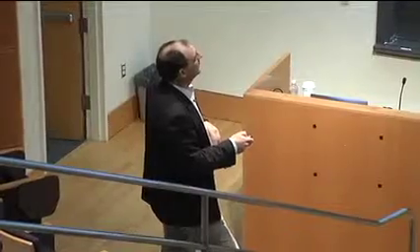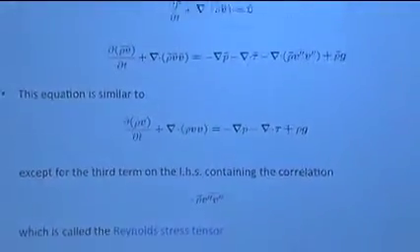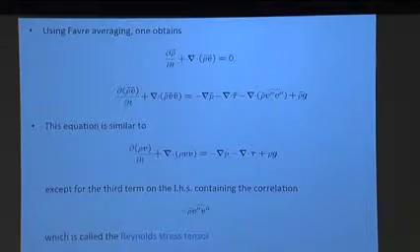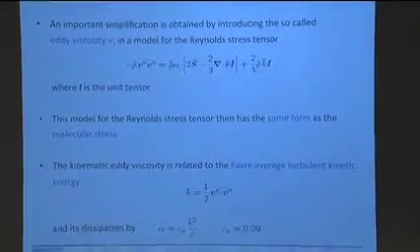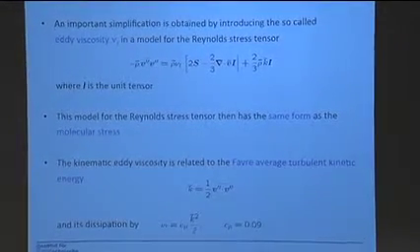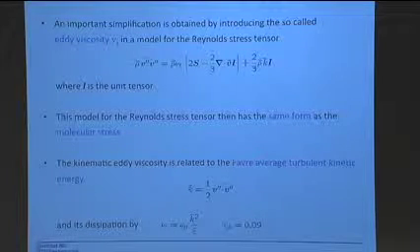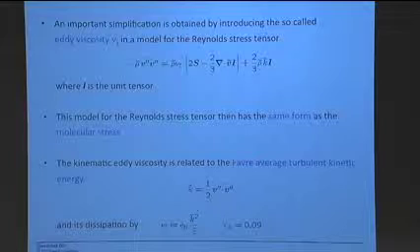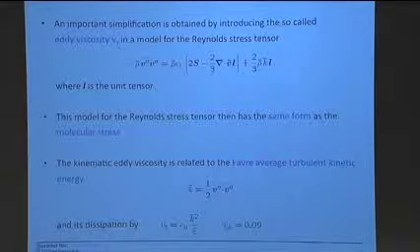And so here, Reynolds just said, no, not Reynolds, but what we do here is we say, well, if that is mathematically similar to this, why don't we use a similar model also? Okay. So this is the so-called eddy viscosity model. We say this here should be proportional to the strain tensor, and it should be proportional to a transport coefficient. Now, this is not the molecular transport coefficient as a property of the fluid. This here is not a property of a fluid.